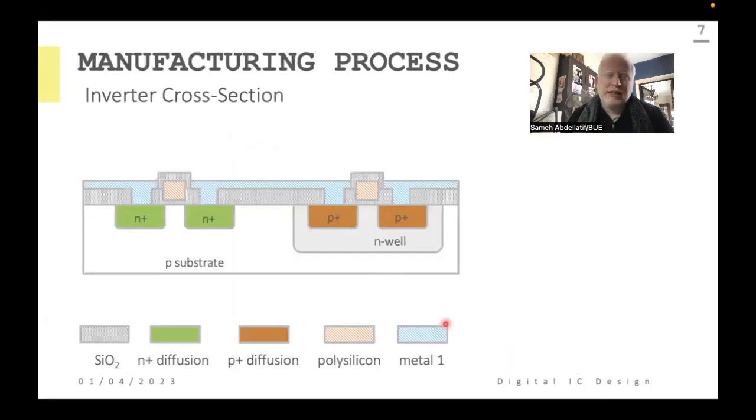So this is the CMOS technology, as you can see. We have here a P-type substrate. We have this N-well so that we can construct the PMOS transistor. And then we have the metal gate here for the P-type and N-type. We have also a similar transistor, but in a complementary way, in an N-side way.